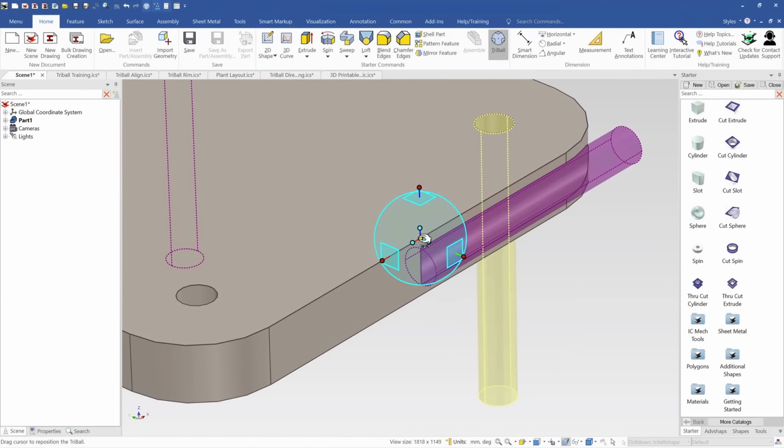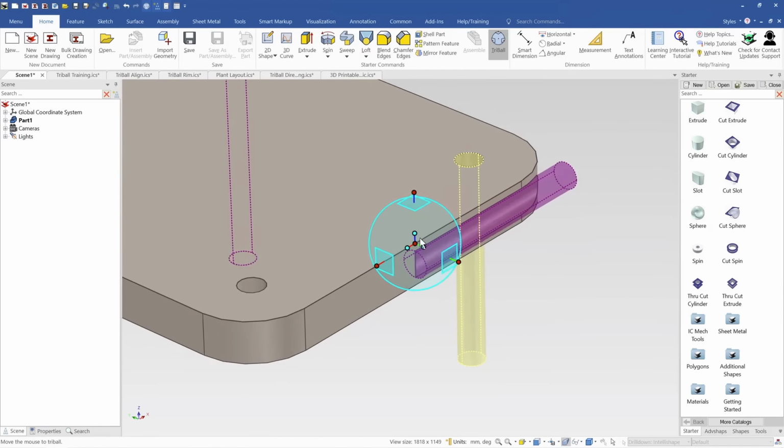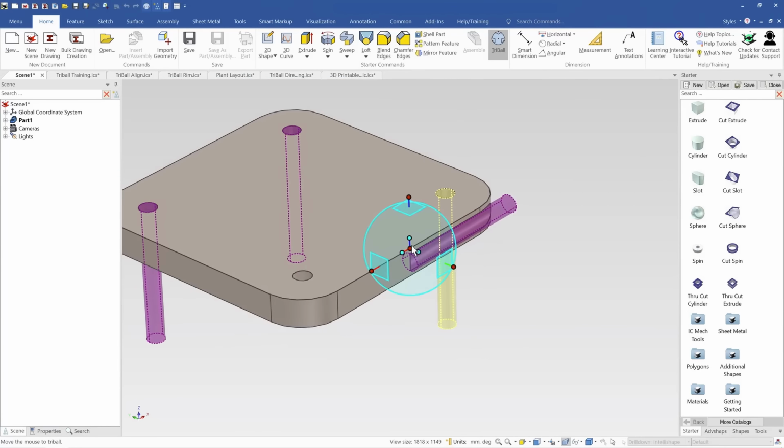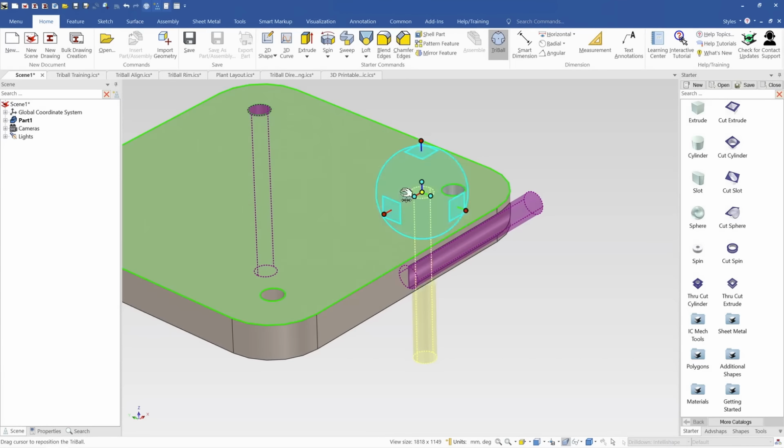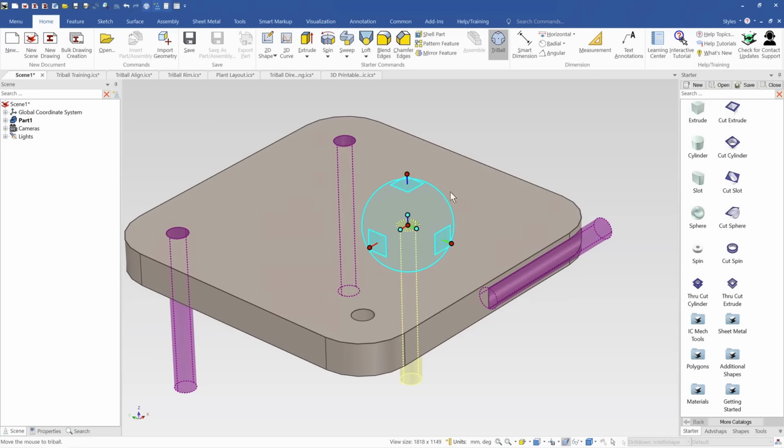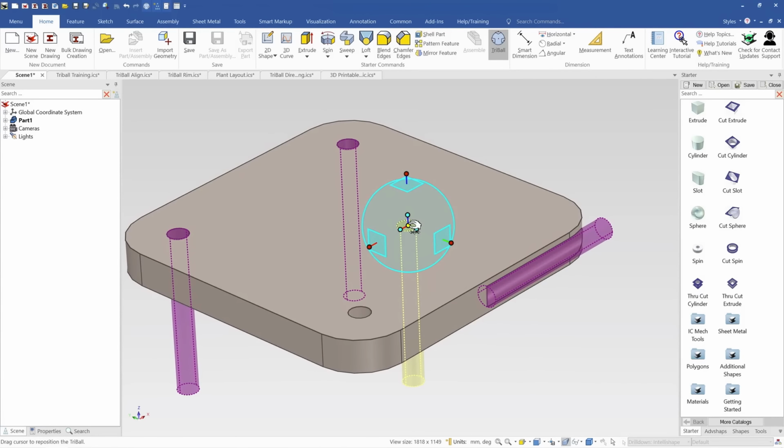Okay, now let's move on to the center of the TriBall. And this is likely the most powerful area of the TriBall. I'm going to reposition the TriBall here just quickly, and then show you a few different options using the center of the TriBall here. As you can see, we can simply drag an item around using the center like that. It's really quick and easy.